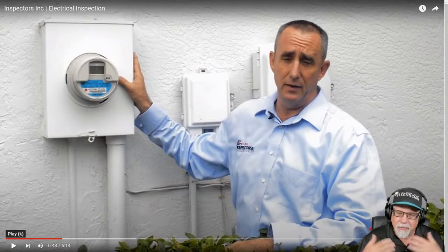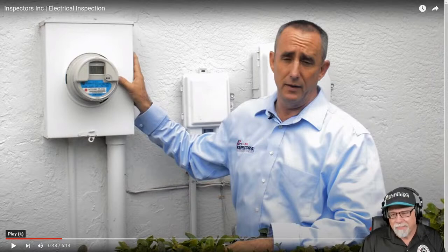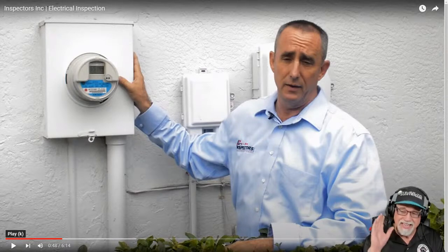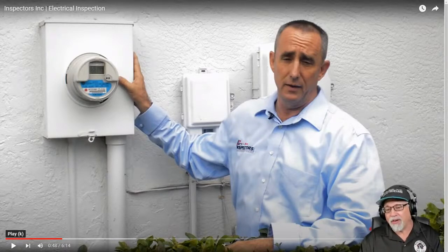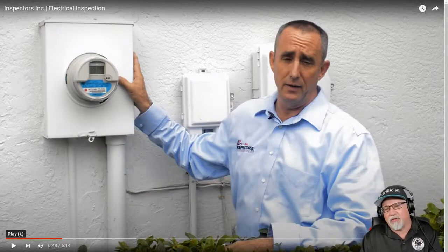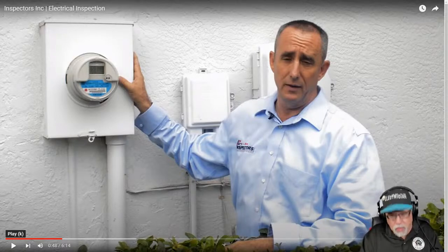All right, let me stop him. And so this is where the information starts to get a little bit misleading, and it might just be because of how he's saying it. So the metal water piping that's in the building, that has to be bonded. Okay, that's a bonding requirement. If he's talking about the grounding electrode system and the water pipe, it has nothing to do with the metal piping inside. It has to do with whether or not it has metal piping outside that's in contact with the earth for at least 10 feet, and it qualifies as an electrode in accordance with 250.52(A)(1). If it qualifies as a water pipe ground, okay.